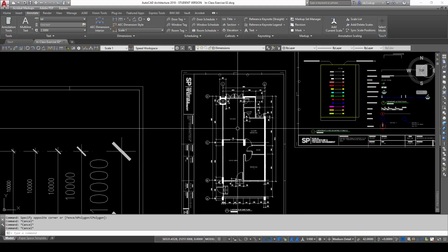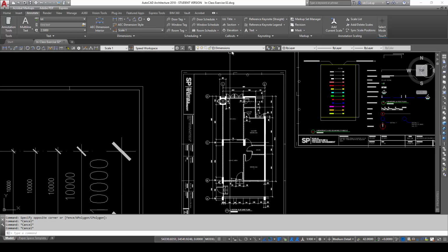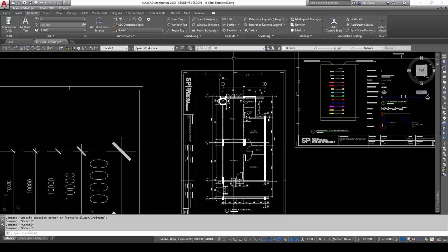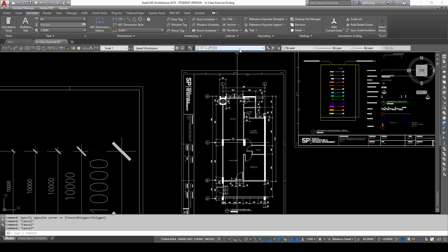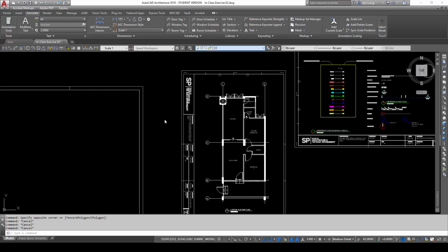Okay. The next thing would be, once we are done with this, for example, I always like to have this habit of acknowledging what has been done and making a good mark of it. So once I know that I am done with, let's say, the dimensions, it's good to check my own work simply by freezing the layer away. So I'm just going to click freeze this layer.